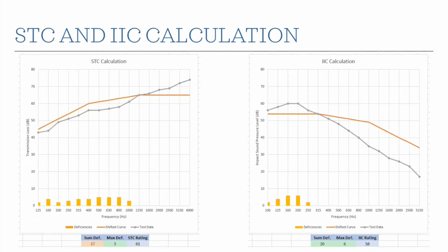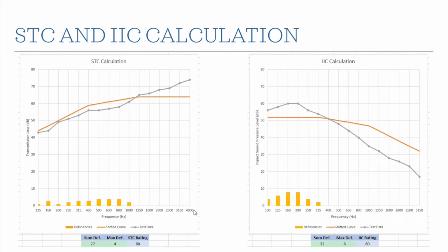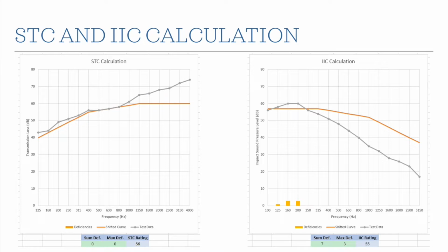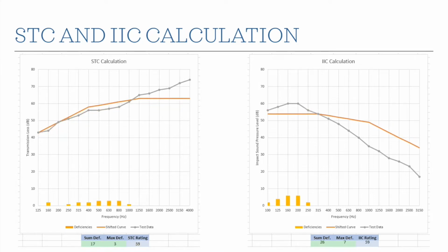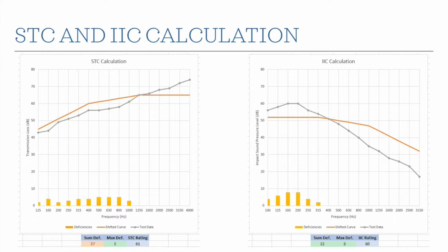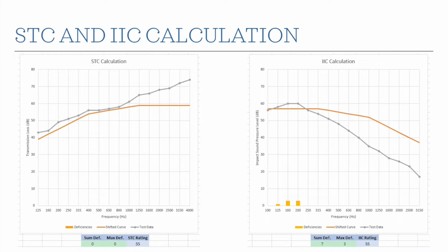So again, we're going from low frequency at the left to high frequency at the right. And in this case, higher levels mean more noise reduction, right? Which is good. So bigger numbers are better here. But we've got these values at all these different frequencies. How do we take that and turn it into a single number STC rating?